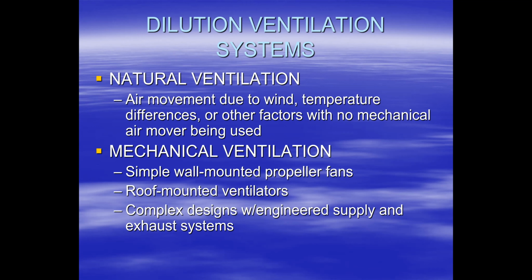It can be as simple as the old axial or propeller style fans, the fans or a box fan that you might use to cool yourself off, even in a residential structure, to very complex designs where they're bringing air in at a certain place or taking air out of a certain place, and it's very much engineered and designed. There are some minimum requirements for those designs to ensure that the air clears out the contaminants away from the workers or by diluting it from the workers. And we'll talk about that in a little bit.